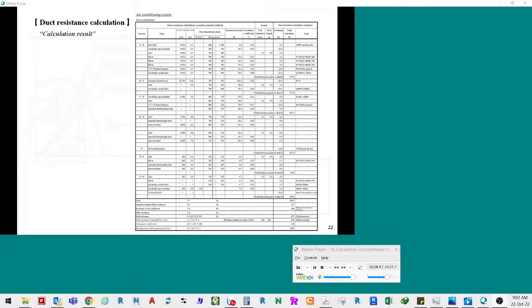In particular, significantly high resistance may be generated in the circuit of the fan where the wind velocity is high and the airflow is unstable. The pressure loss at joint portions of fans is referred to as system effect. That system effect will be briefly explained.